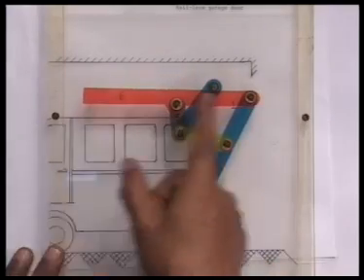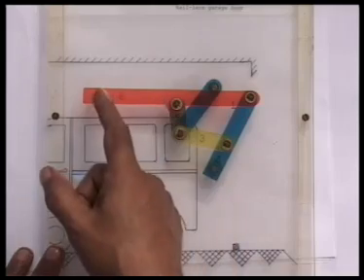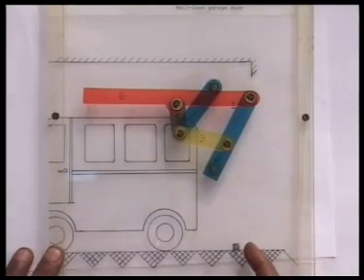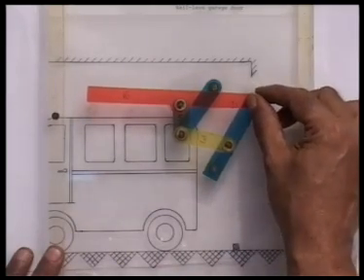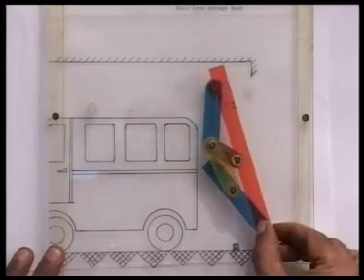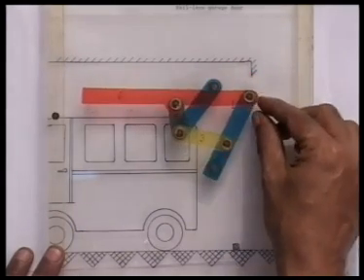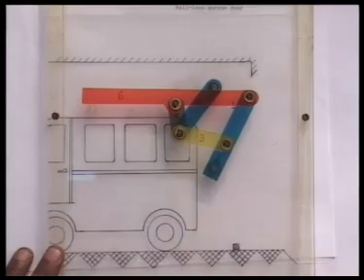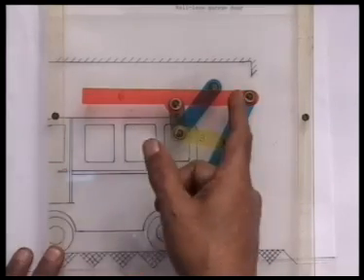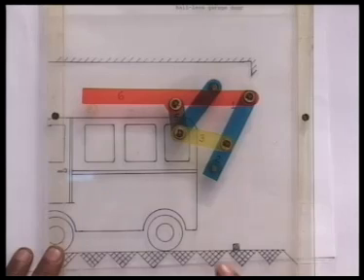Thus, the motion of this garage door board is almost horizontal and then suddenly falls to the vertical position. And such a movement is not possible by using a simple 4-link mechanism with the door board as the coupler. So we go for this 6-link mechanism.